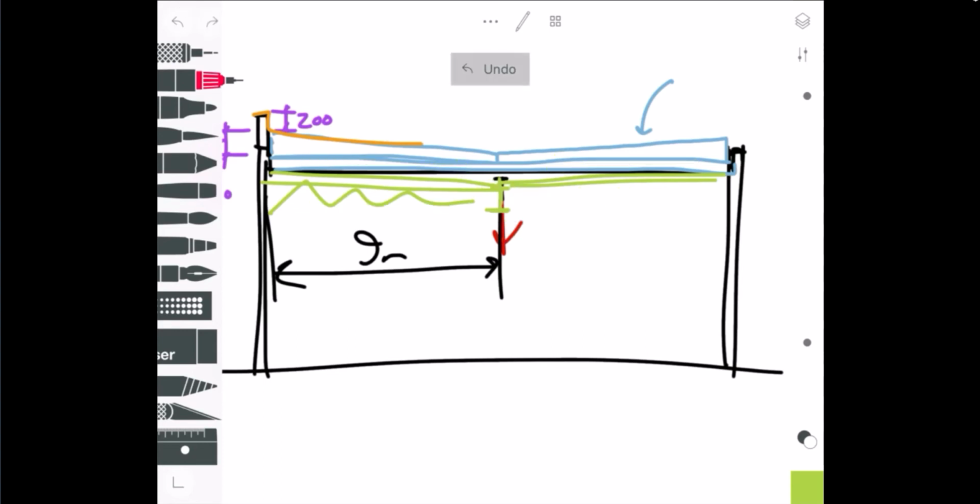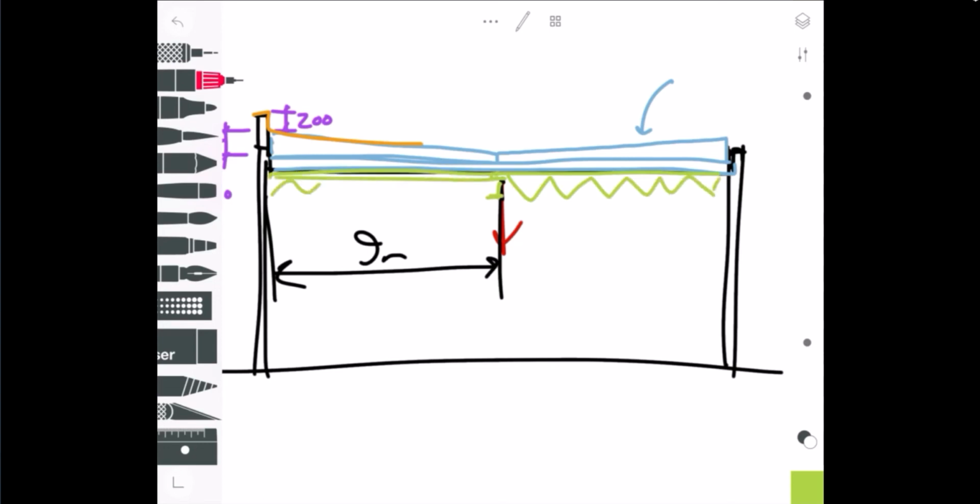So if we just go back to our sloped insulation situation and draw in this structure, you'd have a beam in the middle. I guess I should put my joist seat in there, but whatever, you get the point. You have the beam in the middle, and you have your joists. So you've paid for that anyways. You paid for that joist, you paid for that joist, you paid for that beam. Why not just slope it?